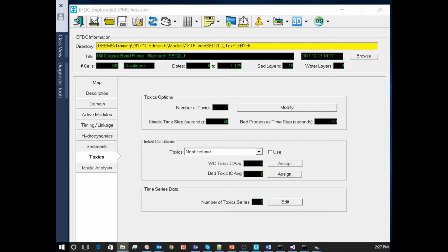The biggest thing you've got to decide is how you split the HSPF constituents for water quality into equivalent bins for the kinetic model in EFDC. If you're doing water quality modeling, that can be anything from just doing a few simple fractions to, in one application, a guy who wrote a whole big program to do all the splits. It was quite an involved process.